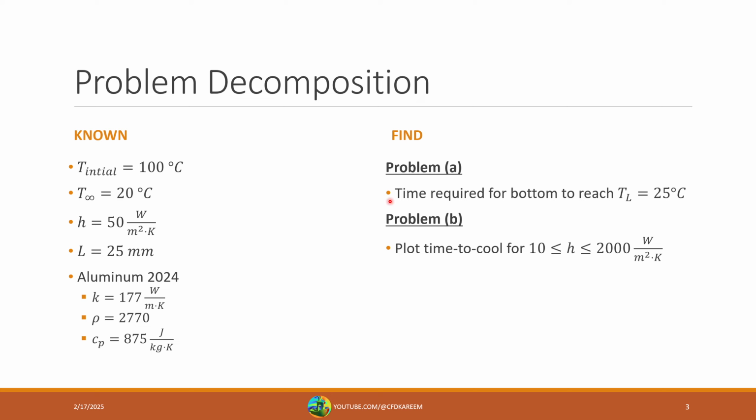In problem A, we're asked to find the time required for the bottom of the chuck to reach a temperature of 25 degrees Celsius. And for problem B, we want to plot that time to cool for convective heat transfer coefficients of 10 to 200 watts per meter squared Kelvin.